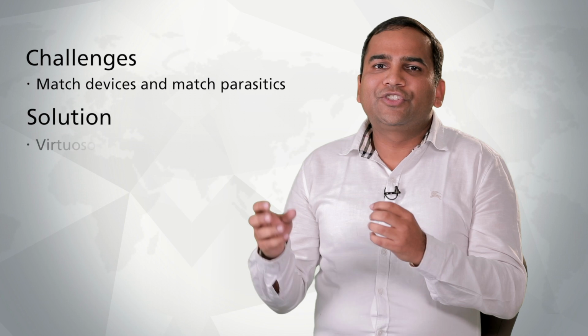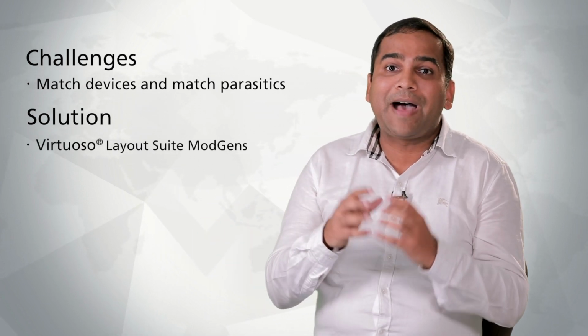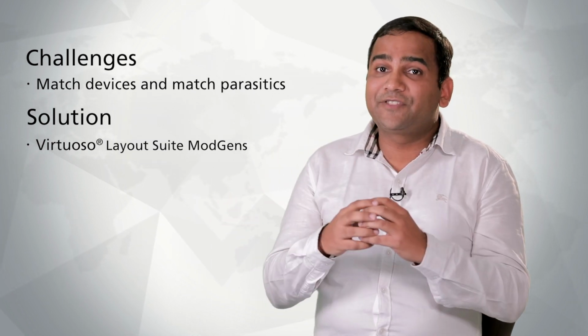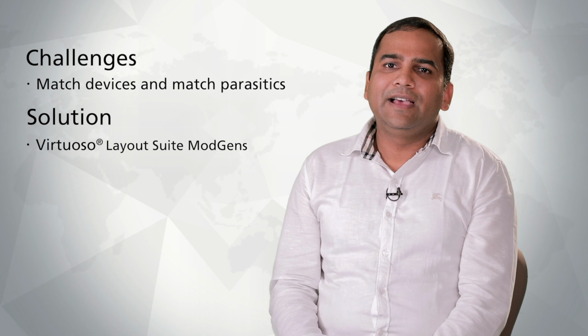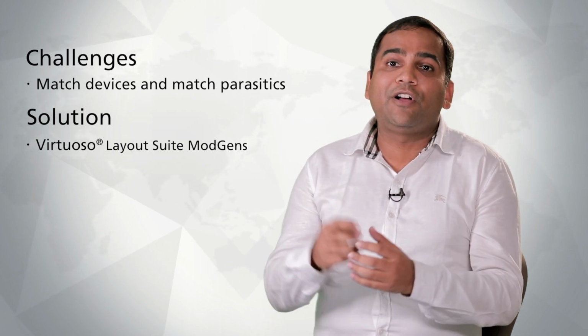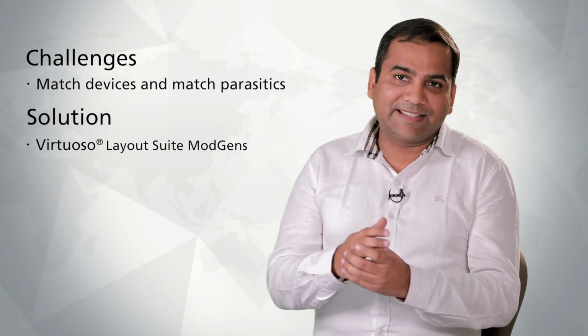Now this becomes a challenge which is difficult to solve if everything has to be done manually. So with the help of ModGen, which is provided by Virtuoso, we are able to match the parasitics and the routing on top of our devices and get a complete good solution in the first go. So that's the beauty of it, and of course we can also save the patterns that we are using in ModGens, and it's a big asset to us.